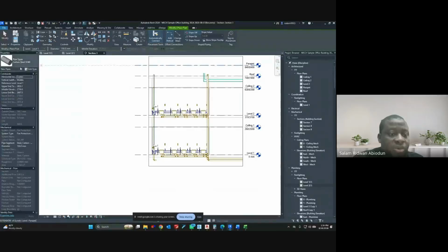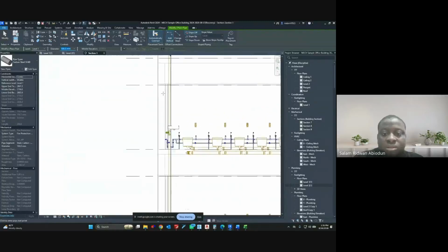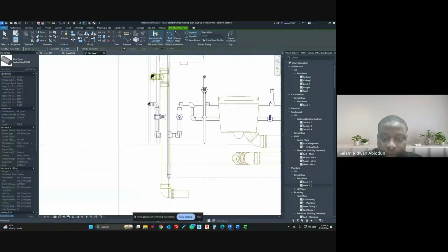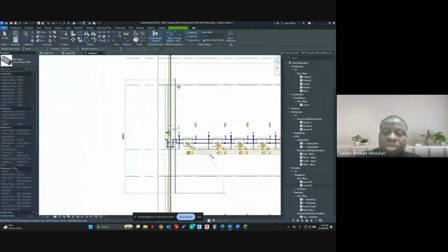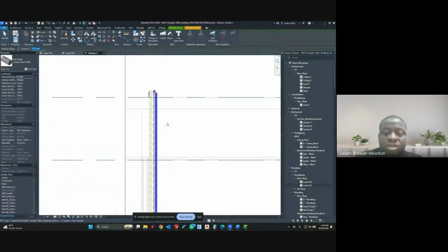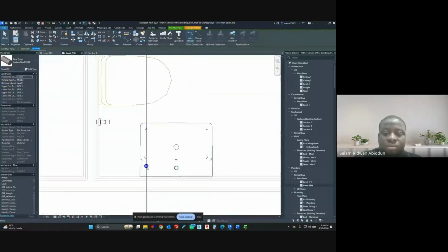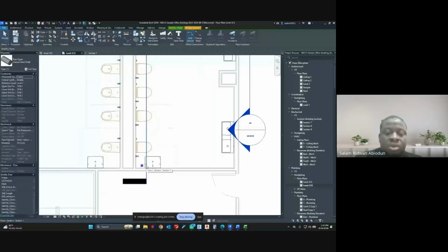What type of pipe am I using? Carbon steel. So I want to make it a 100 mm riser, a 100 mm riser to supply to. Just do it beside this place. 100 mm. So come inside, so I can now see it here. Okay, I can move it. So this will not be our riser. You see now? This will be our riser.